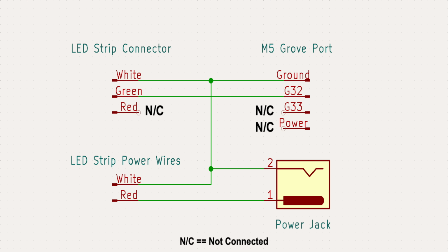The final connection is from the module to the strip. The power lead from the strip is not connected to the module, so leave both red wires unconnected. This is especially important if your strip voltage is anything other than 5 volts that the module is expecting. Regardless, the ground must be shared between the strip and the module, as the signal line requires a ground reference that both can see. We then connect that one signal line, which is green in most cases, and we're done